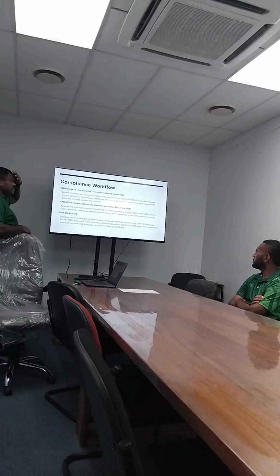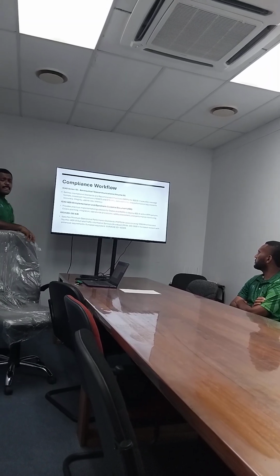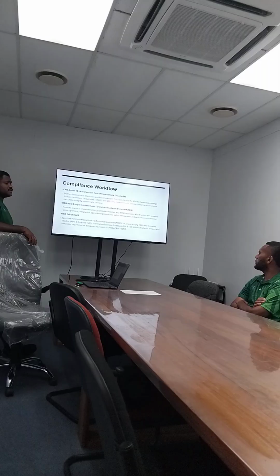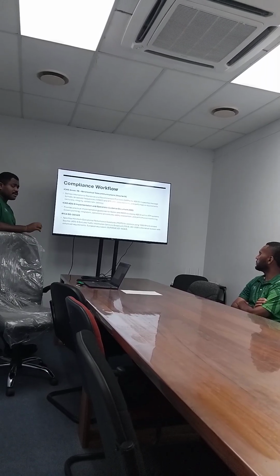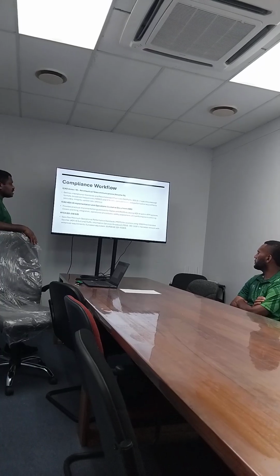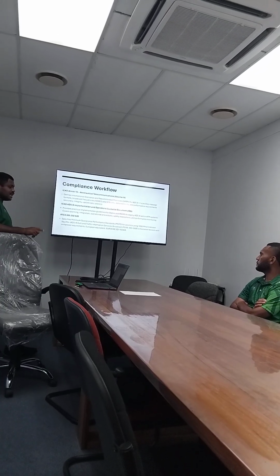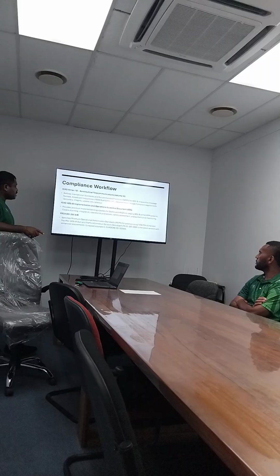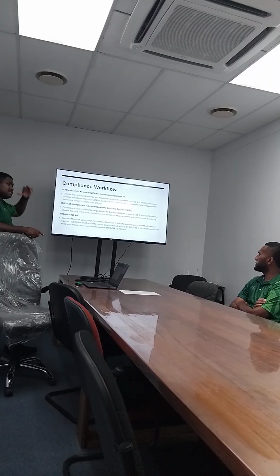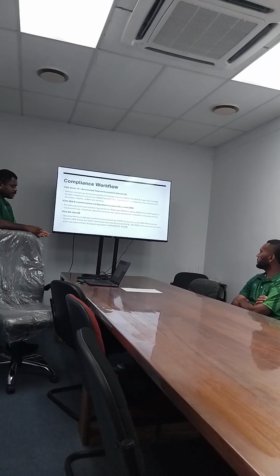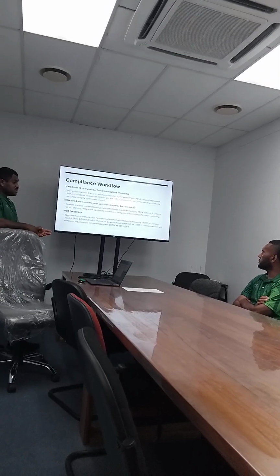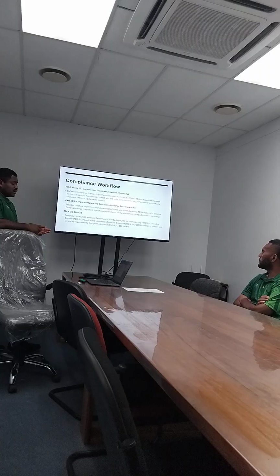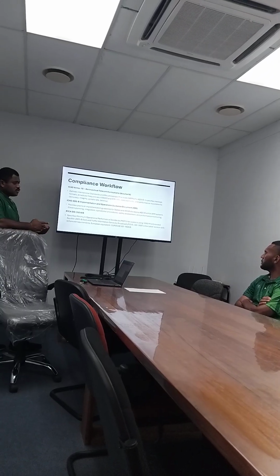This is to do with extended squitter. Before, all the old aircraft, you see the Cessnas, were transmitting ADSB surveillance data, but some of those messages didn't give out the velocity of the aircraft, just showed the registration and aircraft type and so forth.